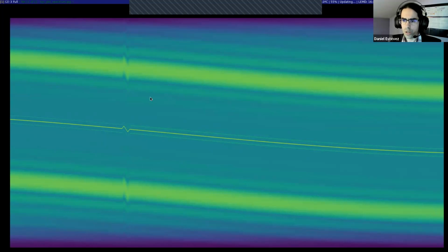That's a question which comes often. At the same time, both of the subcarriers are transmitting the same information. It's just split in two parts. Each of those gets 50% of the signal power. And the reason is just because it's simpler to split it in two pieces than in one piece. You could imagine this one not being present and only an upper subcarrier. So that's more complicated to deal with than having two subcarriers. So that's the reason we have two, but then we need to combine them back.